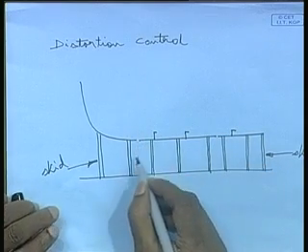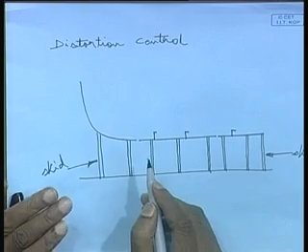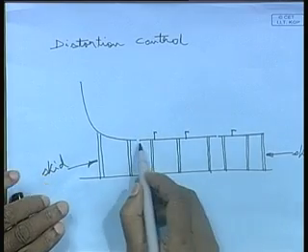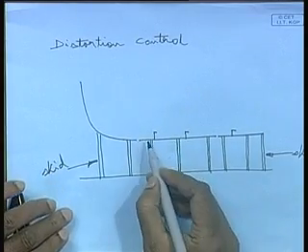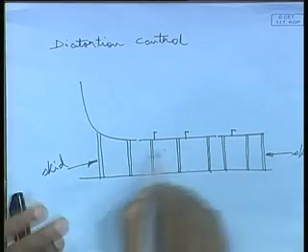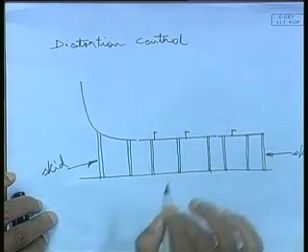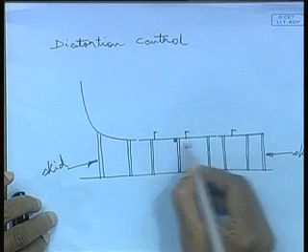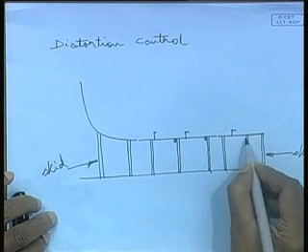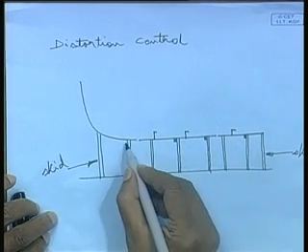Now, as you know, to do proper welding you have to maintain that root gap uniformly. So, for maintaining that, after alignment, when the welding process starts, such that the plates do not move, the general practice is you put some lugs here and fix them to the skid.